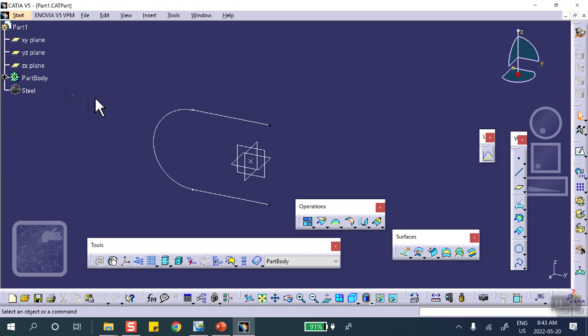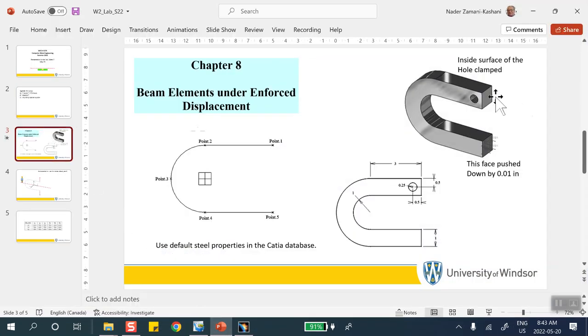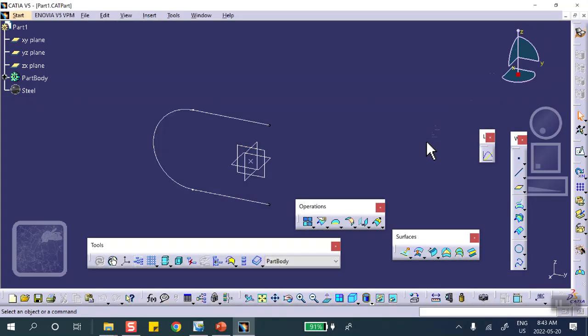And the other thing is, do not solve this problem with solid elements, because on the test we may be giving you drawings like this and say, model this problem with beam elements. Use the most appropriate, we tell you. Then don't look at this and say, hey, here's a solid, so I'm going to do it with solid elements. You have to use beam elements with this problem. All right, we will tell you that. Okay, sometimes we will tell you, sometimes we don't. Because if I drew this thing like that, you will say, hey, I know it's a beam, but this is kind of bulky, and there's a hole there. You can't do it with beams, etc.